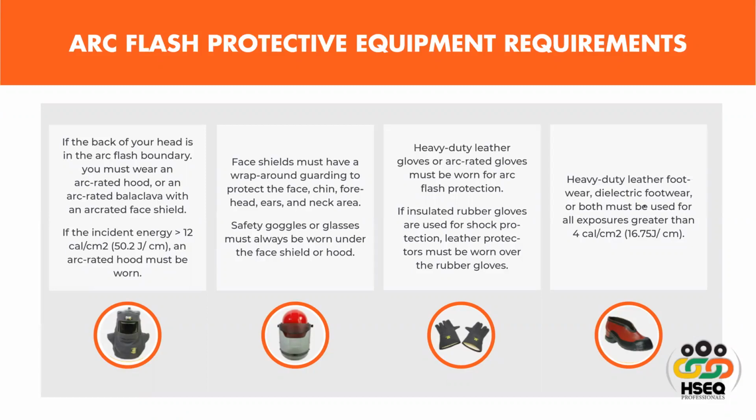If insulated rubber gloves are used for shock protection, leather protectors must be worn over the rubber gloves. And the last one is heavy duty leather footwear, dielectric footwear, or both must be used for all exposure greater than 4 cal per centimeter squared. So this is the requirement that either heavy duty leather footwear, dielectric footwear, or both must be used for exposure greater than 4 cal per centimeter squared.